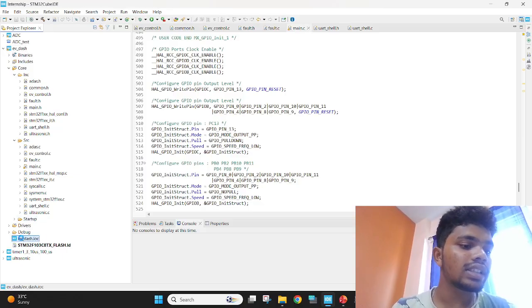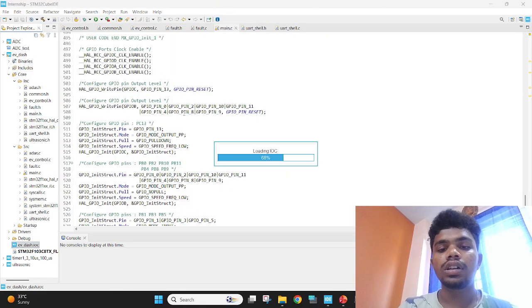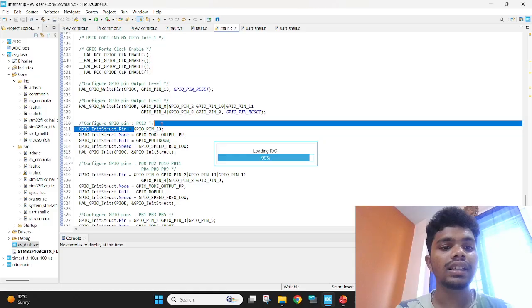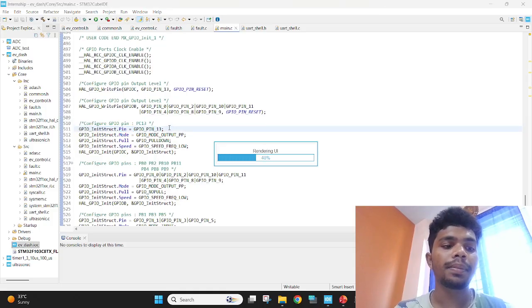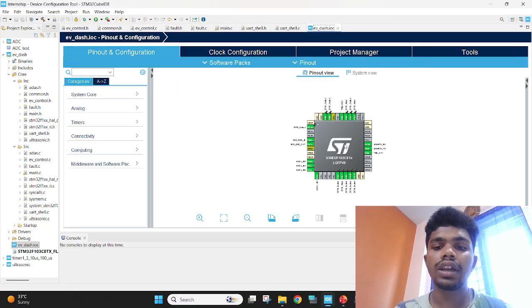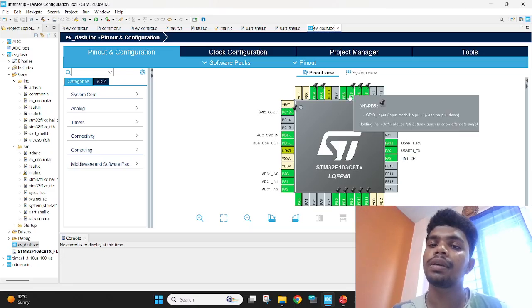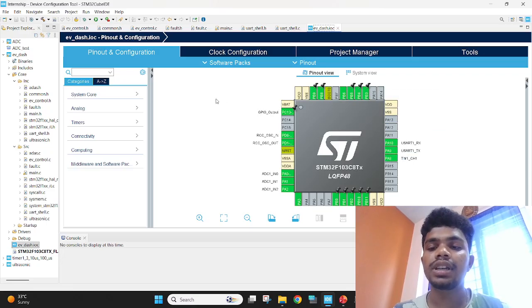And this is the IOC, where the microcontroller chip pin settings are. We set up the pins like this and called them in the spare parts in Proteus. Here you can see that we assigned pin values like PA0, PA1, PA2 and PA3 for one purpose, PB0 for one purpose, and PA10 to PA8 for one purpose. Every pin has been defined for its own purpose.